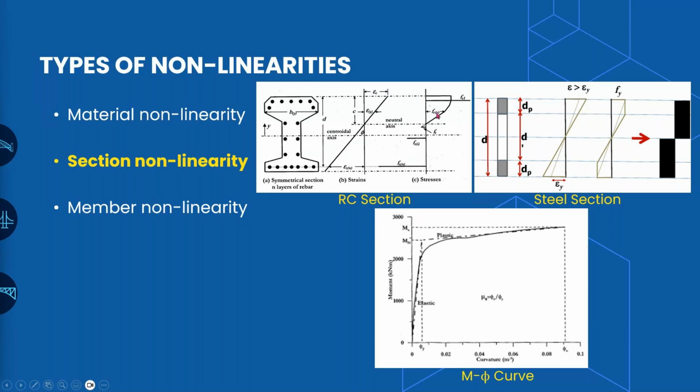The stress curve which is generated is very common, a parabola for concrete, then a small amount of strain with respect to FT, and Fs are basically the stresses with respect to the tensile reinforcement. The generation of these stress strain curves for concrete takes place at each point.